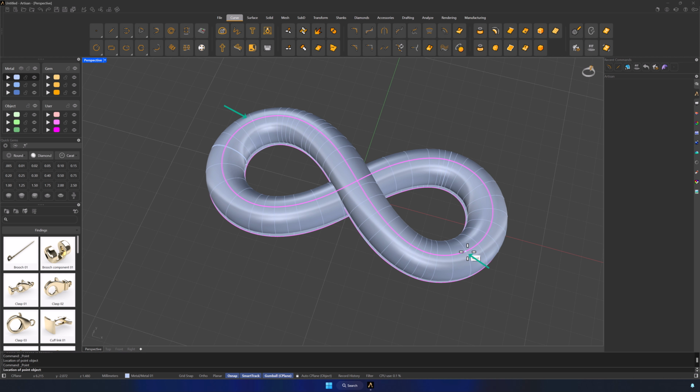Once created, select the ISO curve and use the Split command. Then select the 2 points as separation points and press Enter. You can delete the rest of the curve. Select the remaining curve and create an offset on both sides of 1 millimeter from the top view.